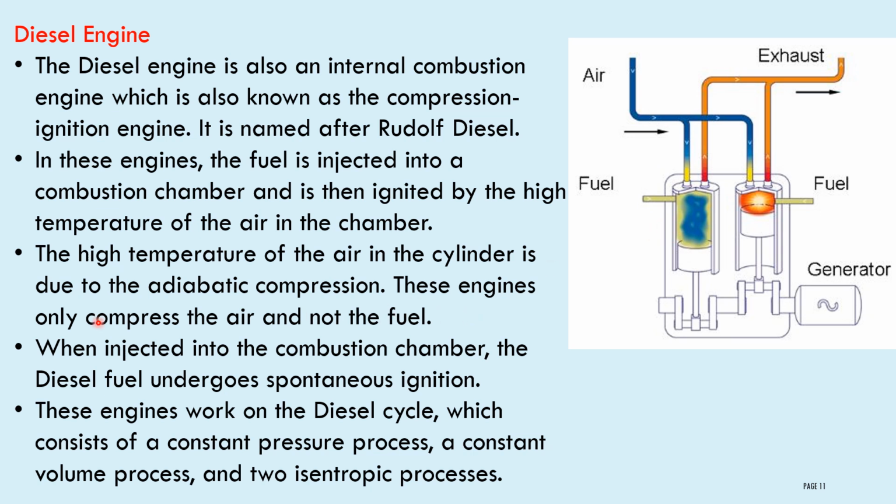This engine only compresses the air, not the fuel. This is very, very important. This engine compresses only the air; it will not compress the fuel. When injected into the combustion chamber, the diesel fuel undergoes spontaneous ignition. Spontaneous means the diesel itself starts igniting.